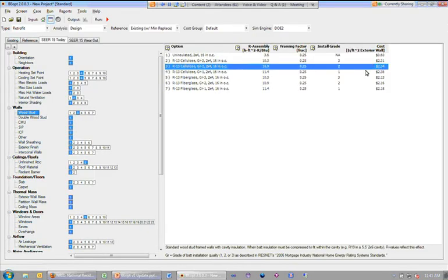So this is the aggregated cost that includes both labor and material, the sum of both labor costs and material costs, and for each one of those there could be multiple. For example, material costs could include the cost of framing plus the cost of cavity insulation separated out. So we have a lot more detail in the underlying cost of BEopt so that you can change just different pieces of those costs if you have better information, or override the entire cost altogether.